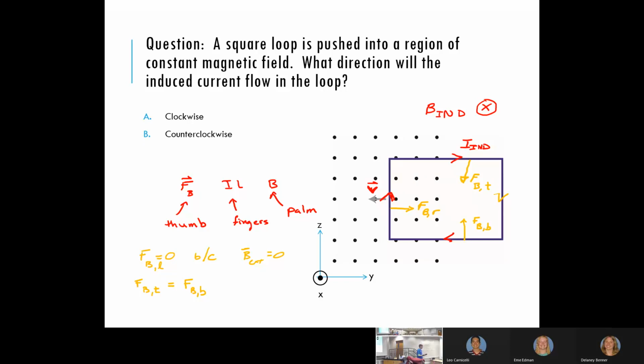You'll have to get your brakes fixed. You'll have to get your brake pads changed out. And you know when that happens because manufacturers are smart. They put a little piece of metal in the brake pad. And when the brake pad wears down to a certain spot, that metal starts touching the rotor. So you get a metal-on-metal contact. That's that screeching sound. That is an audible warning that your brake pad is low. Take it in and get it changed. If you do it early enough, then it doesn't affect the rotor and you can keep going. You just change out the brake pads and everything's good.